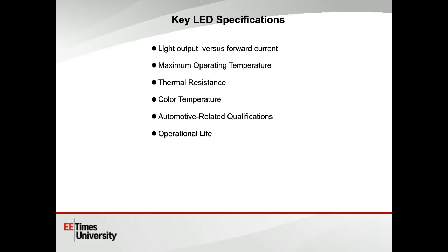So, for example, a specification may say something like, after 15,000 hours, 50% of the devices will still give 80% output at a 90% confidence level. It's a complex specification, but they have tables specifying the performance of these LEDs over different operating lives.